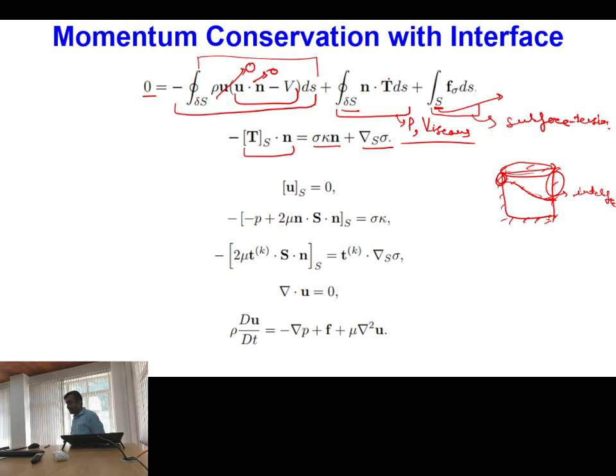Minus P into I, because pressure will be acting along only the diagonal plane, plus delta ij into Sij, where Sij is the deformation tensor, which is equal to, what is deformation tensor? Del ui by del xj plus del uj by del xi. Okay. So everything you have forgotten, because already also we have discussed about this.